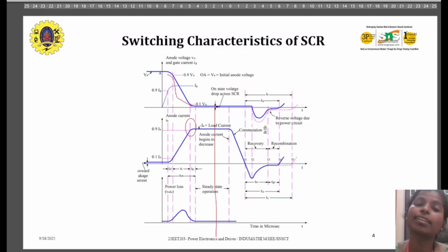So it is used in low and medium frequency rectifiers, general SCRs, and inverter choppers require fast SCRs. So it depends. So the switching characteristics of an SCR are turn on delay, rise time, spread time, and turn off delays. It has reverse recovery time.